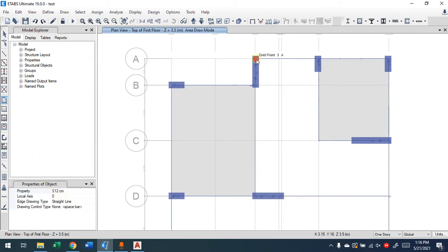This starts with a click. You'll click and you'll see a line. You'll click here, then you'll click at this point here. Then you'll come to this joint here. You'll follow the perimeter of the slab. Let's say here, I'll come back to this point here. Then when you reach the first point and click, that's it, it will draw this slab for you.